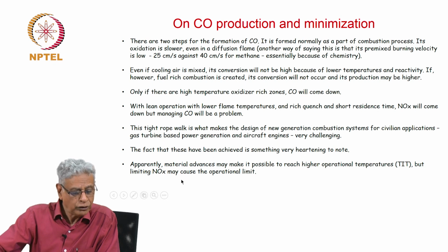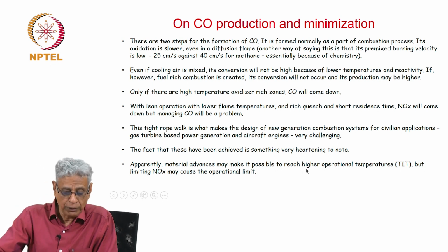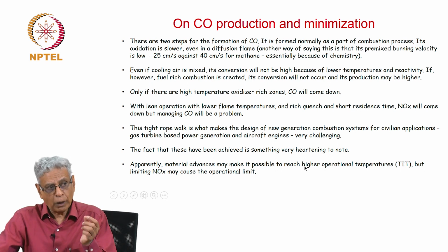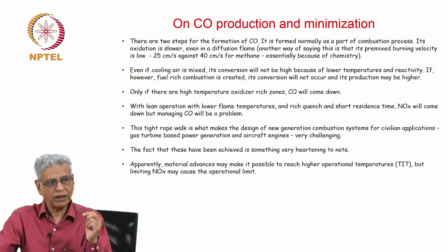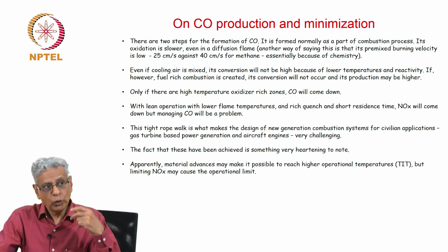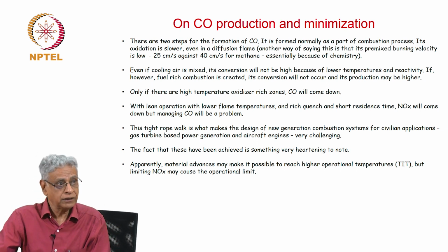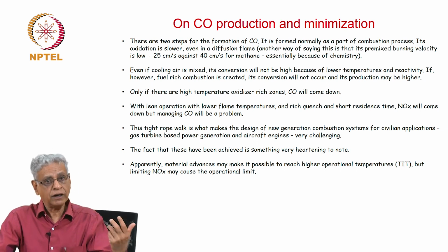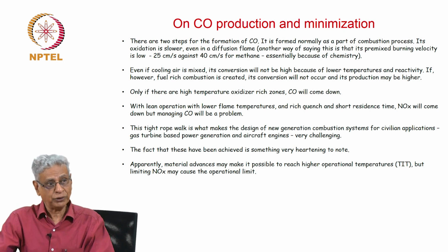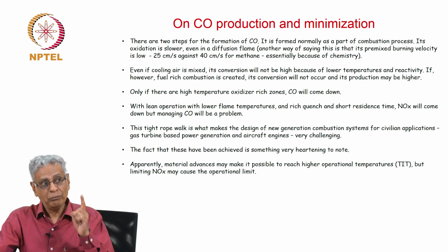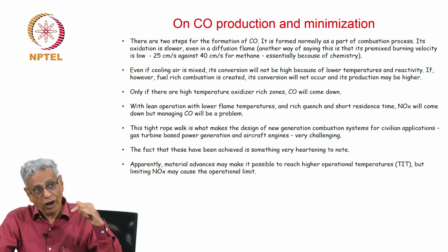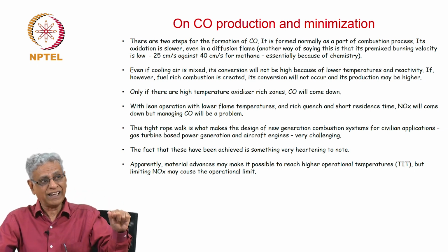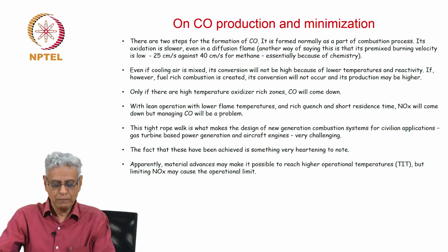But limiting NOx may actually become the operational limit. That is, the turbine is the controlling element for limiting the temperature of the entry of the gases into the turbine. You may use advanced materials, cooling techniques, thermal barrier coatings, which are standard in this whole process, to raise the inlet temperature. It may be possible to build an engine, but the emission may be so much more because the temperatures are really high that the NOx emission may become the limiting factor for the design, not so much the material and technology.